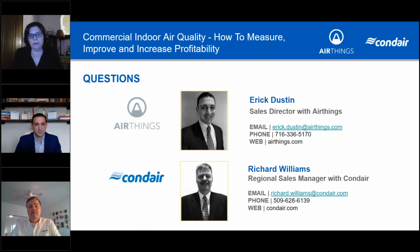Great. I have one for Eric. If we are going to monitor IAQ, where do you place the sensors? Oh, that's a great question. Thank you. So really, we like to look at the space, but there's a few general recommendations. So our sensors, if it is open space, will be able to monitor approximately 2,500 square feet of space.